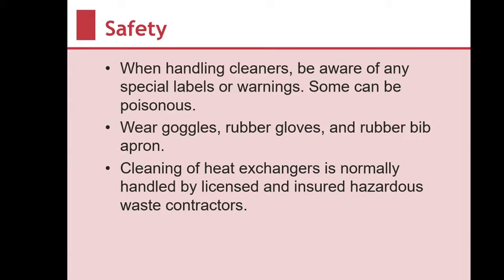Safety. When handling cleaners, be aware of any special labels or warnings. Some can be poisonous. Wear goggles, rubber gloves, and a rubber bib apron. Cleaning of the heat exchangers is normally handled by a licensed and insured hazardous waste contractor.